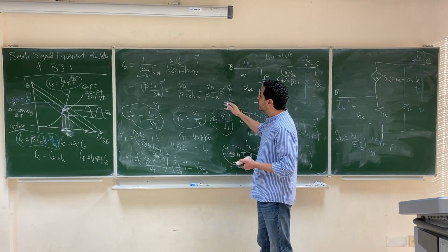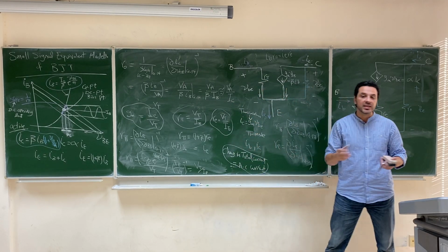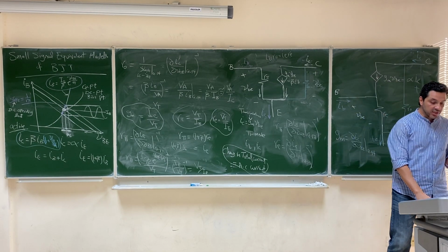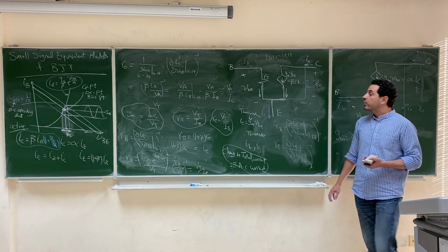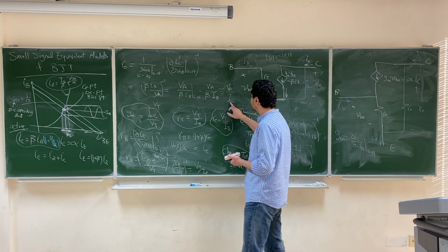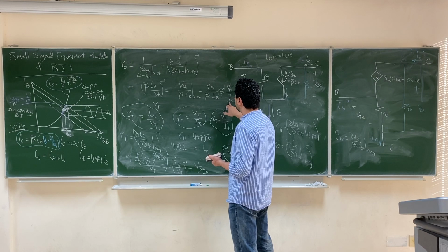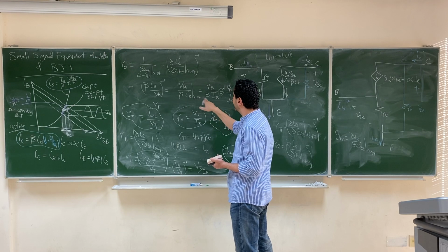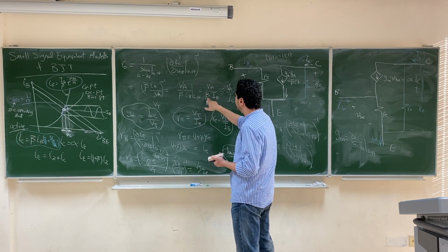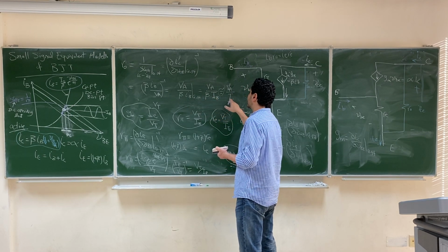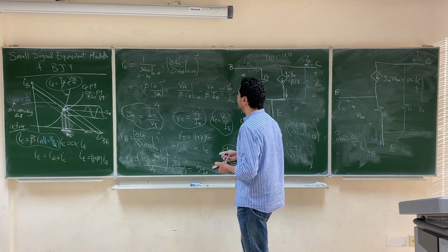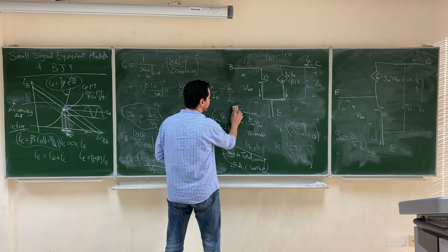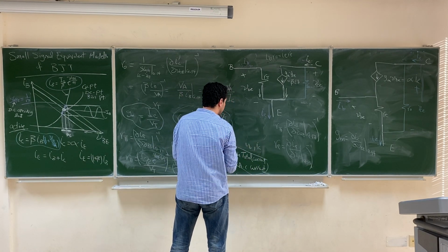Okay? So here the RO can be calculated as VA, the magnitude of the early voltage, divided over the collector current, the DC component of the collector current. So when you substitute here with the Q point, the total I base at the Q point is the DC value of I base. Beta multiplied by the DC value of I base is approximately the DC value of the collector current, and from here we can calculate, or we can say that RO equals,